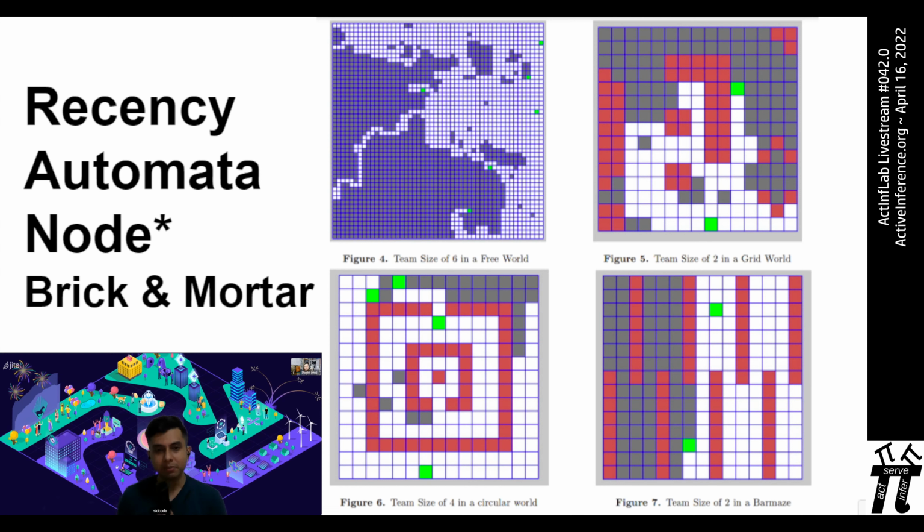And then there were very simple approaches which were more suited for the digital world, such as simply node counting, that is, how many robots have visited this node before. So every time you visit any square, you just increase its visit count by 1. That helps the robots in understanding, okay, this area has been visited 5 times and the surrounding squares have only been visited 2 times, so I should maybe explore the unexplored regions first.